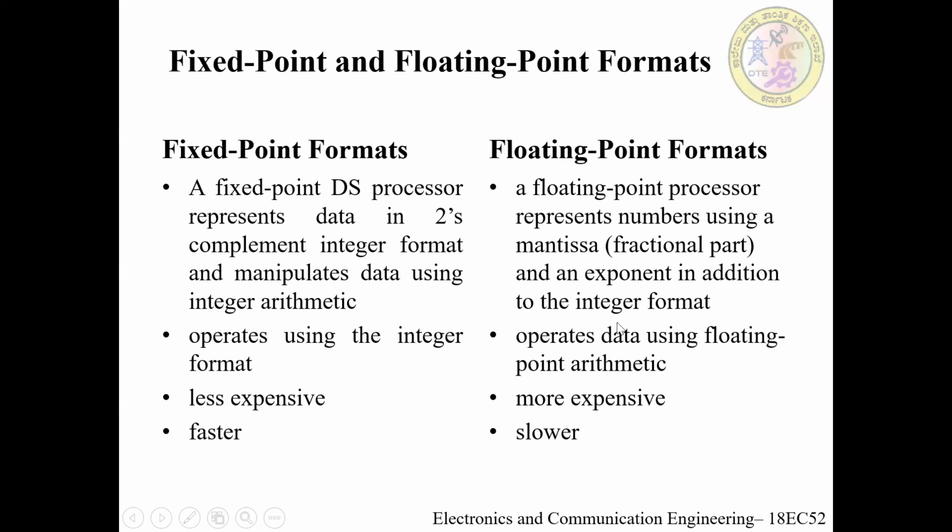When it is time to make the DSP an application specific IC, a chip designed for a particular application, a dedicated hand-coded fixed point implementation can be the best choice in terms of performance and small silicon area. The format used by a DSP implementation may be fixed point or floating point.